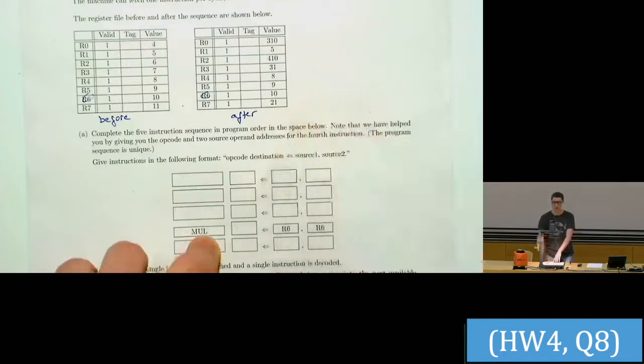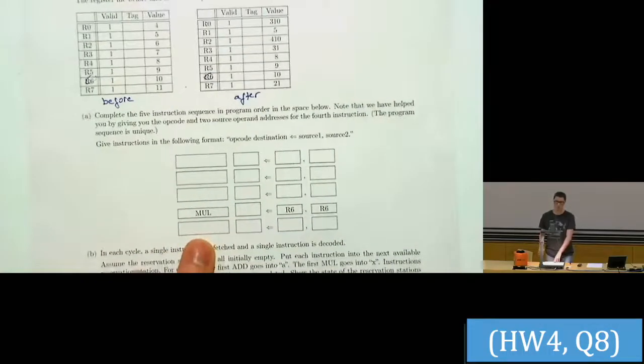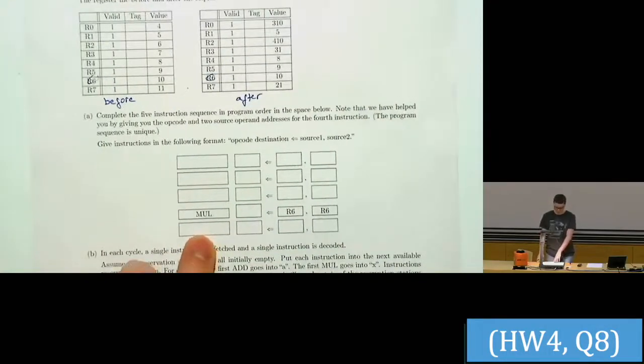So some other instruction has overwritten this 100, right? And there is only one possibility because we have only one instruction coming after this multiplication instruction here. So we don't know exactly what is the destination register, but just by considering this information, we can tell that the destination registers of those 2 instructions are the same.